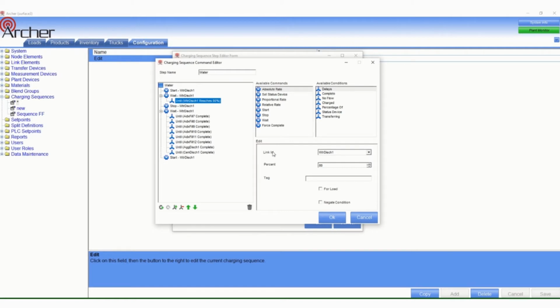In this case, Archer will wait for all the materials to finish discharging before releasing the remaining water. Commands are processed from the top to bottom as they appear in the instruction set, and for the sake of argument, they process instantaneously unless a condition is provided to interrupt its flow. In other words, using the example above, placing commands only without conditions in the instruction set should not allow the water to stop discharging any time before it's emptied.